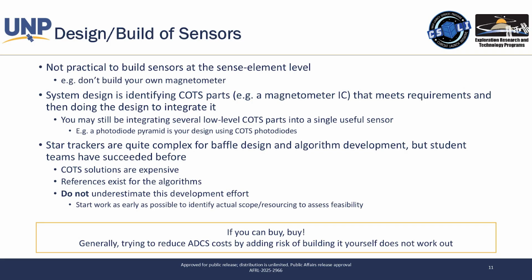Obviously you have your efficiencies and stuff, but you're gathering all the energy you can. And so it falls off as a cosine. It takes 30 degrees before you've dropped by, what is that, about half, right? So you can be pretty grossly off before you really notice a whole lot of power degradation. If you're 10 degrees off, you probably don't fully see that in your power generation curves, which is nice, right? There's a little bit of flexibility there.